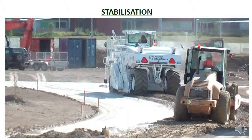This photo shows a lime stabilisation process in action. The lime has already been laid and hydrated. You can see it's the white material on the road. The white machine is a rotary hoe which is mixing the lime into the underlying soil. You can see that the material behind the rotary hoe is a mix of the lime and the soil. The compactor behind the rotary hoe is compacting the lime soil mix. A grader came along after and shaped the surface.